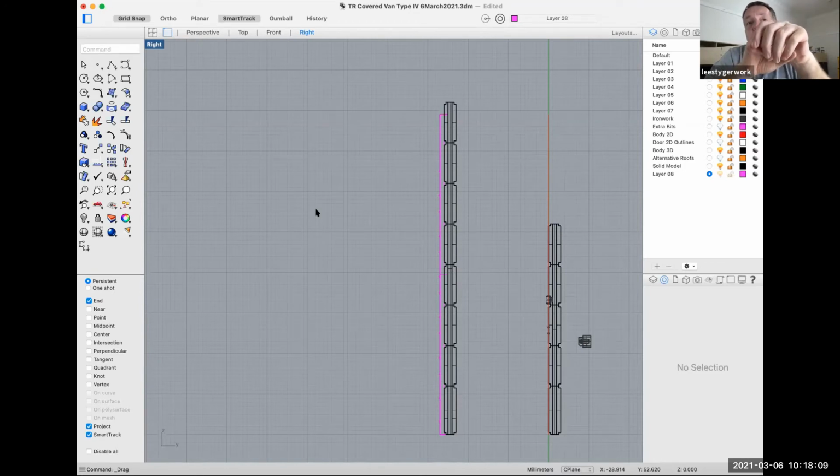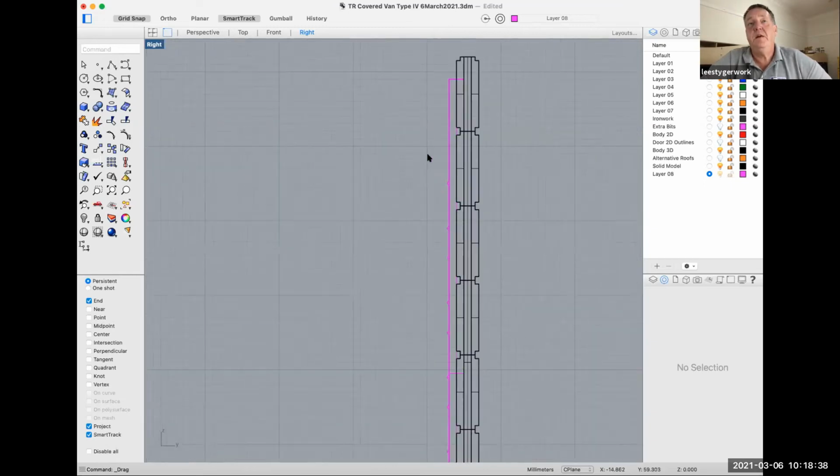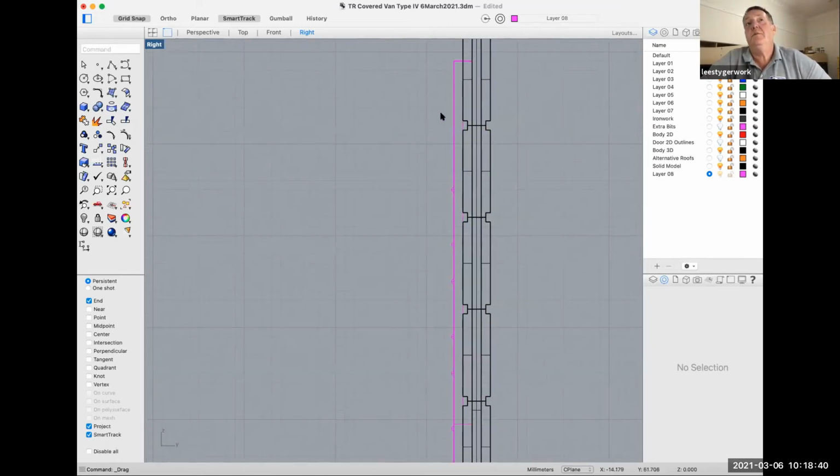But what I found, especially with even the fine scale 3D printing, is that anything under about 1/4 mil, by the time you've primed it, painted it and everything else, you start to lose detail. The CAD system itself will work to, its default is 2 decimal places, so it's working to 3. So should you want finer than that, it'll do it and more. But for my eye and the sorts of things I do, 0.25 is about as far as I go for most things. Now, up until now, we've been snapping onto the grid. Obviously, there's no half size on the grid.